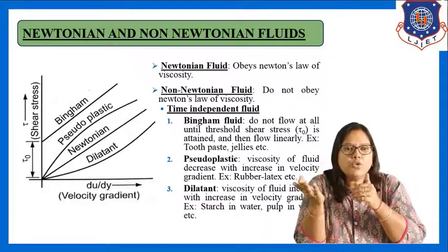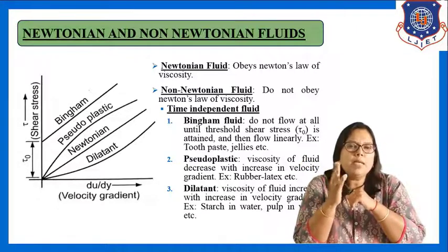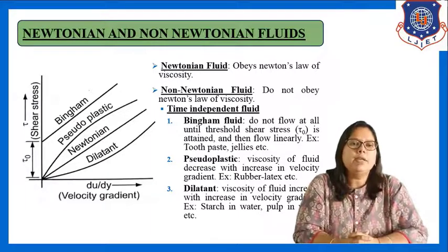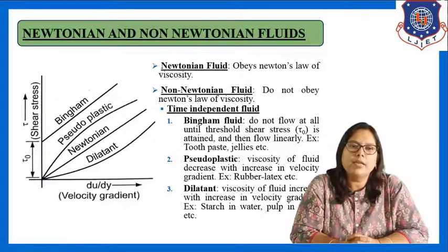And opposite to pseudoplastic is dilatant. You can see the graph also. Pseudoplastic and dilatant nature are completely opposite. Dilatant fluids are those fluids for which viscosity increases with increasing velocity gradient.